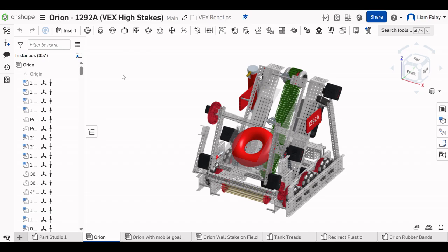So now, what are configurations? Configurations are essentially different variations of the same part, and these different variations allow the part that you make to differ in any way that you can imagine. Variations can be different length, width, style, and any feature specific to your unique part you can create configurations for.